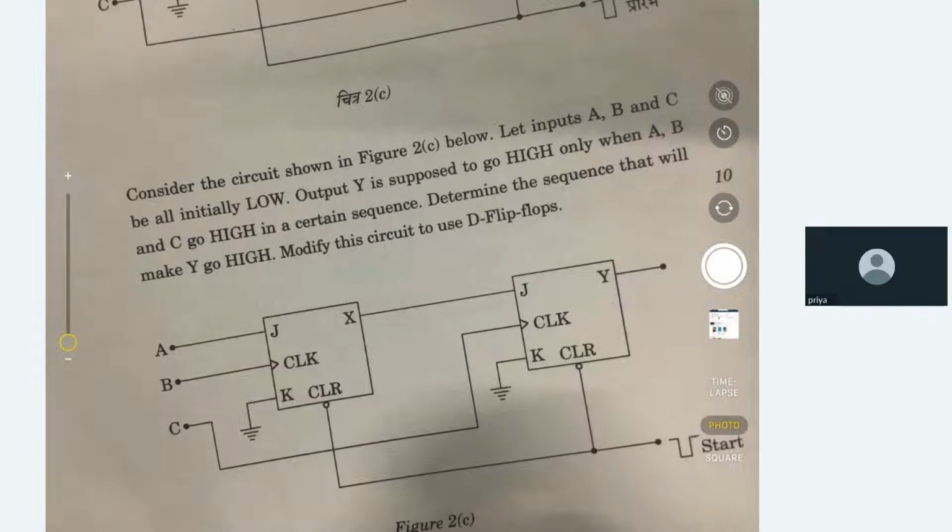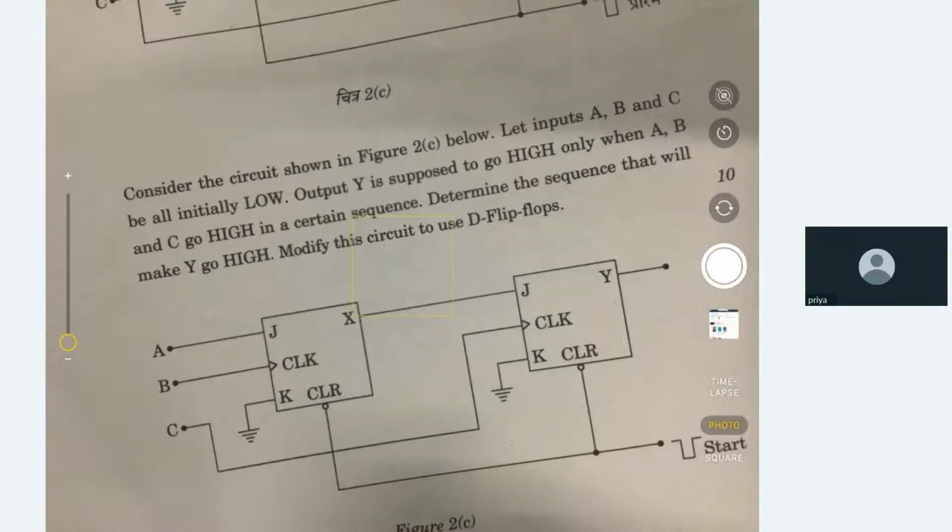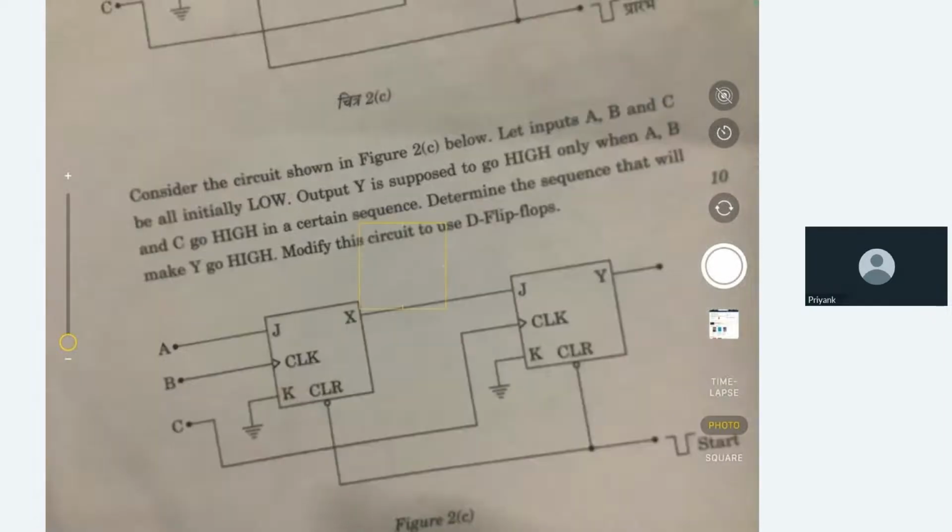Otherwise, simply you can write v(t-1) and show the shifted v(t) curve. Then v(t-2), you can show the curve shifted by 2. And then you can show the curve shifted by 3. And then simply add them. That will give you the answer.